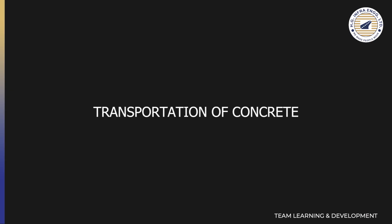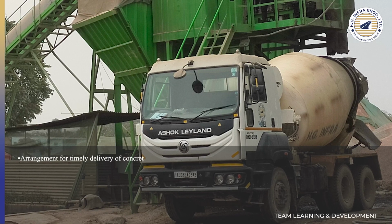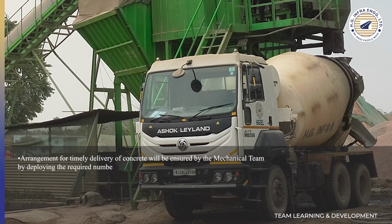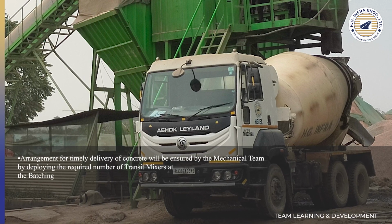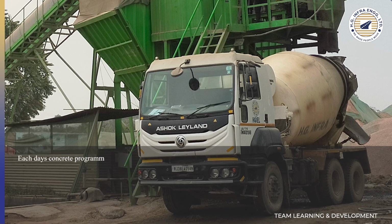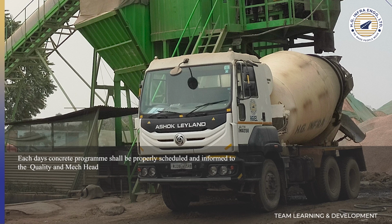Now we'll see the transportation of concrete. Arrangement for timely delivery of concrete will be ensured by mechanical team by deploying the required number of transit mixers at the batching plant. For the transportation, each day's concrete program shall be properly scheduled and informed to the quality and mechanical head 1 day in advance.